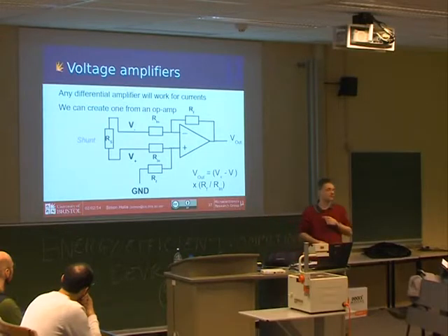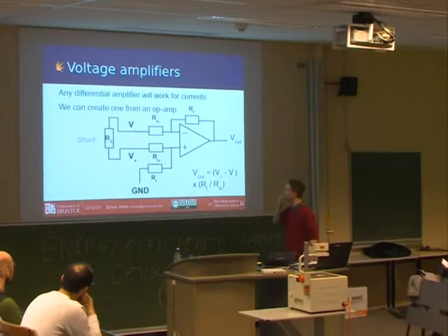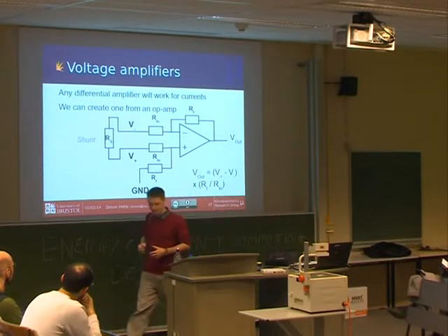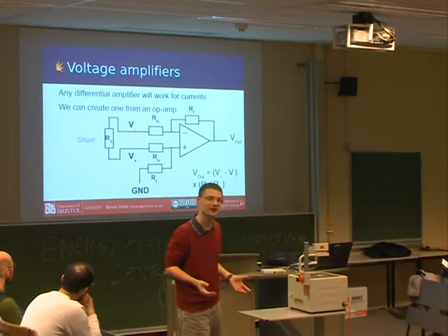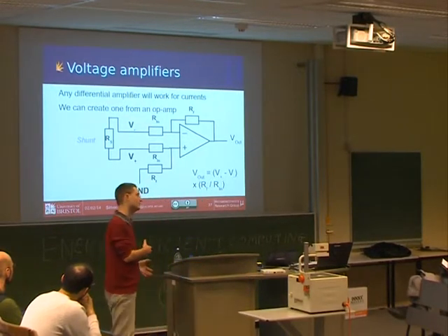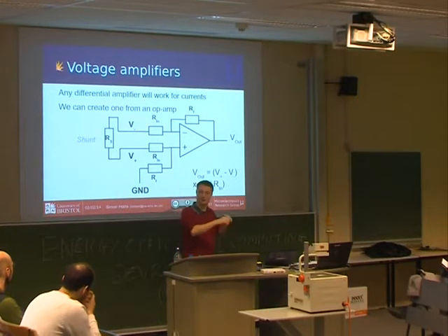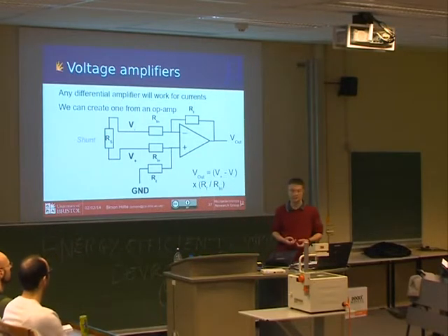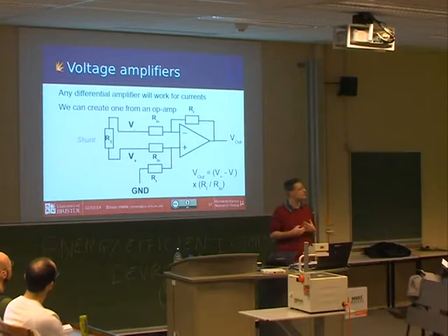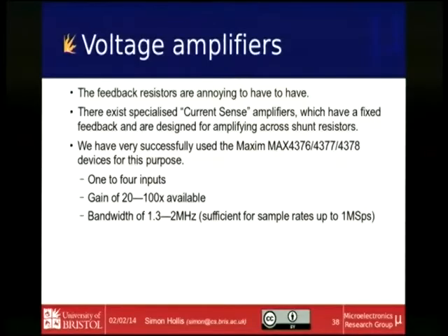The downside to this is, when I started thinking, well, shall I build this circuit, should we make boards based on it? You find out weird things, like the fact you've got 4 resistors here adds more cost to the assembly of your measurement board than it does to buy the operational amplifier. That's because for assembly, the robot has to go to 4 more places, and we've got 4 more resistors, and we've got 2 different values, and there's an actual cost to making this. So if you wanted to mass produce this, there's a way forward that's attractive. And it's annoying, breaks our layout, doesn't look so pretty, all sorts of things.